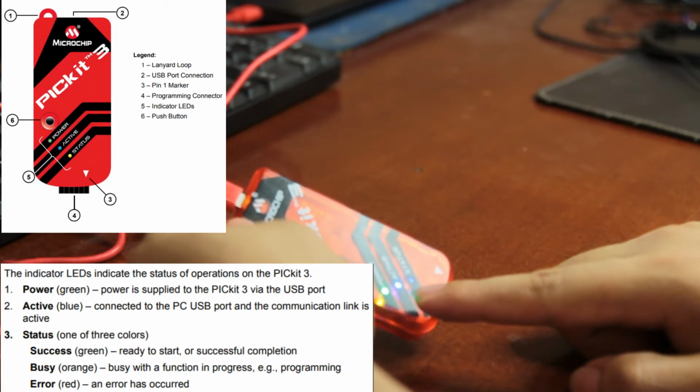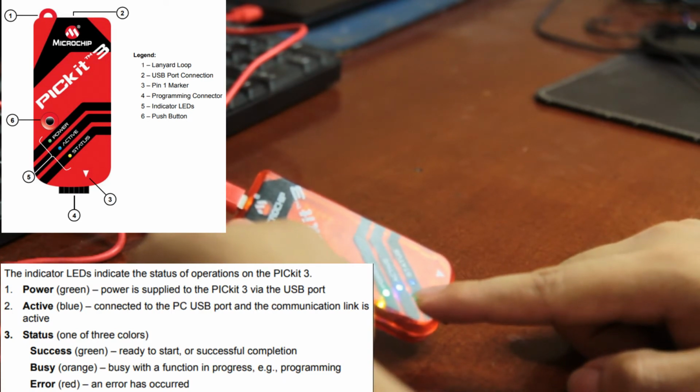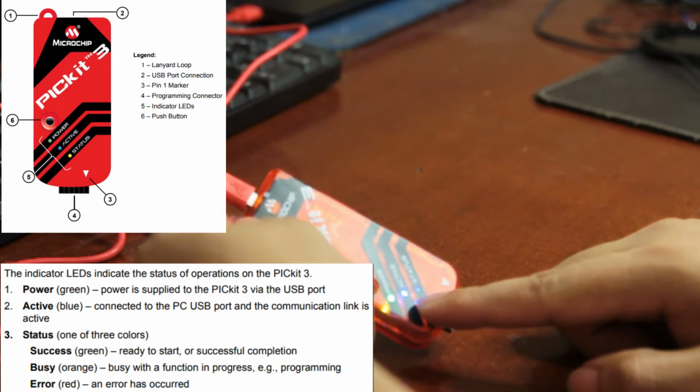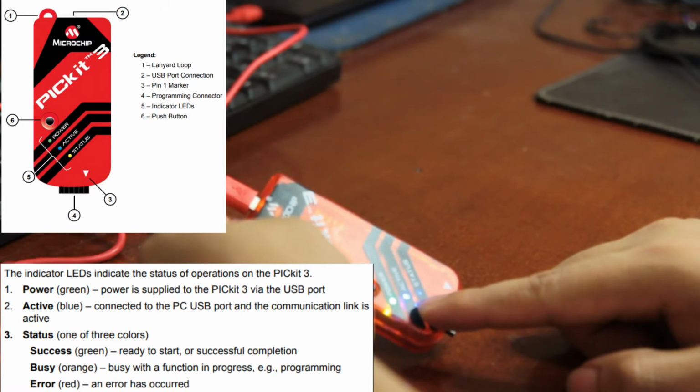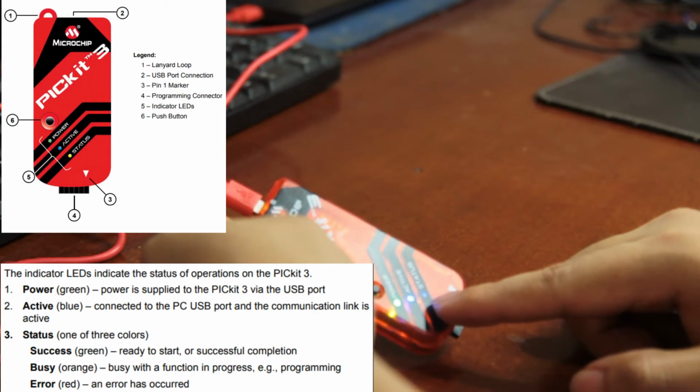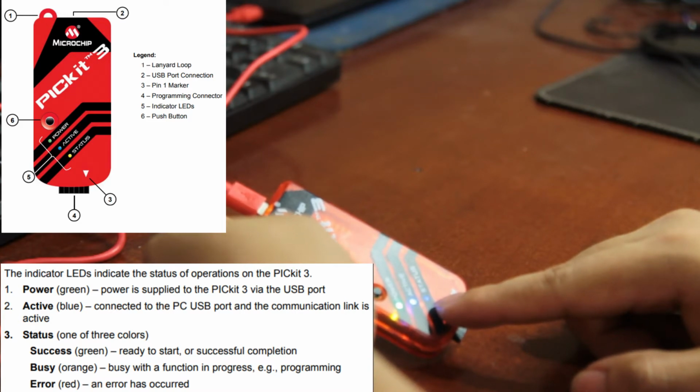If the power is green, it means power is supplied to the PICkit 3 via the USB port. When the active indicator is blue, it is now connected to the PC using the USB port and the communication link is active. The status will light up green if it's ready to start, orange if it is busy with a function in progress or programming. When it is red, an error has occurred.